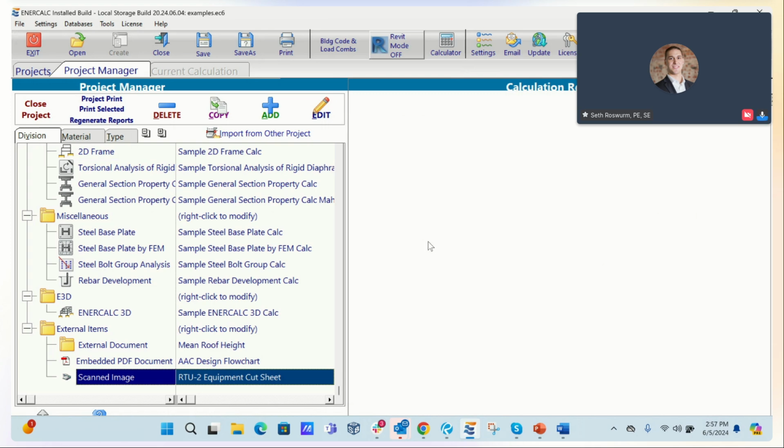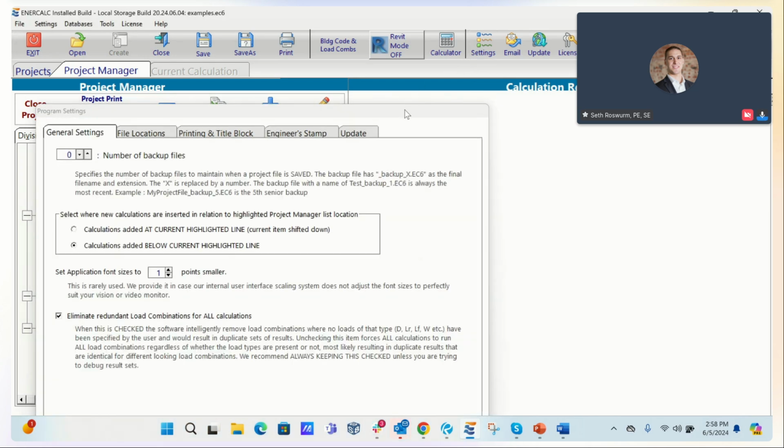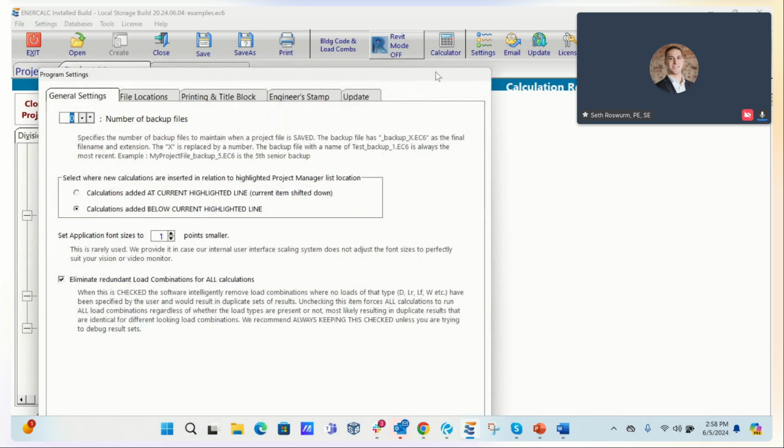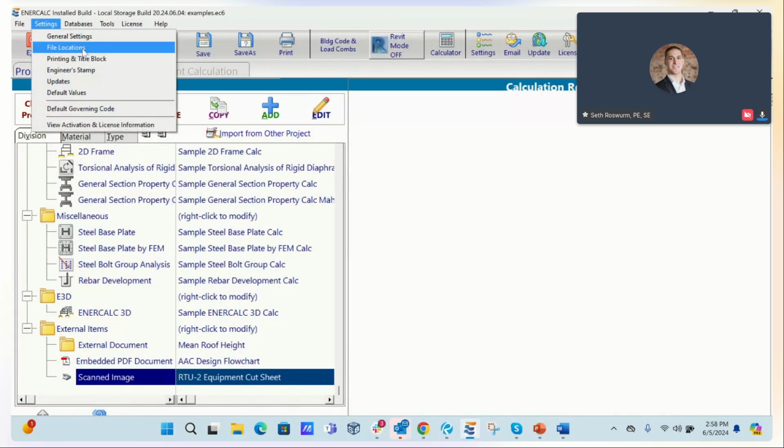The long answer is, and Mac can kind of drill into this, that the load combination options that you see when you're setting up your calculation are not directly linked or inherited from the building code IBC version you've specified. Those are just a preset, out-of-the-box set of combinations. You can actually go and define your own preferred set of combinations, whether those have special modifications, what have you. If you're not familiar with that, look at the top of the ribbon bar in Mac's interface, at the drop-down menu right next to File. You see Databases rather than the settings menu.